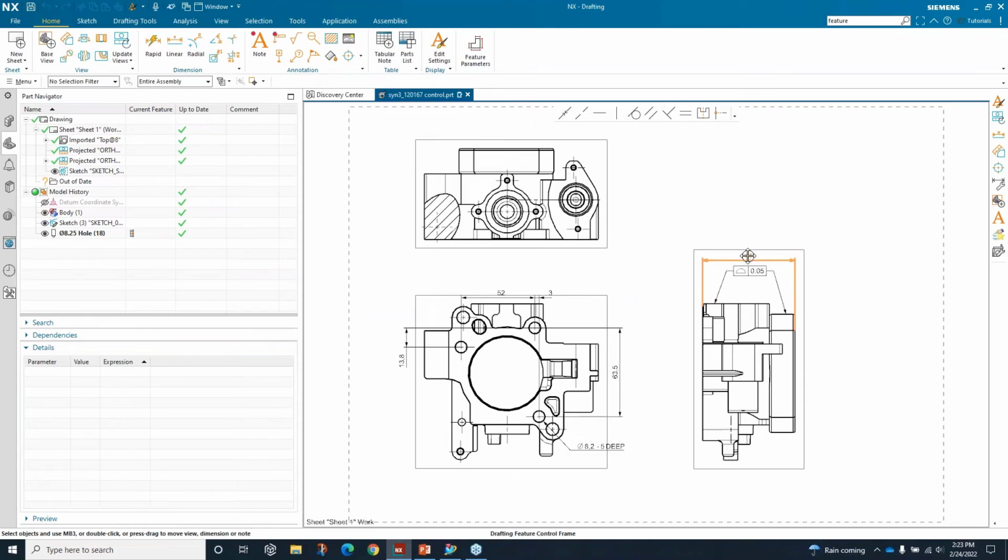And there it is. You'll notice that it's actually making the view grow. And that's because this is the PMI. If you look at the very bottom of my screen, right at 6 o'clock, right down here, you can see PMI linear dimension inherited. So this is a nice thing to do if you're looking to get into PMI, but you're not exactly sure.